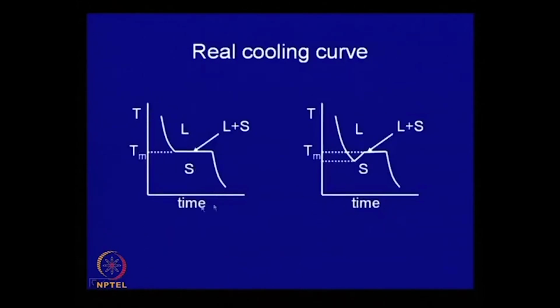here. The actual ideal curve we had initially shown, but here even if you leave it indefinitely at this temperature, solidification will not begin unless you have enough energy to create new surface. That is, the solid-liquid surface is created.